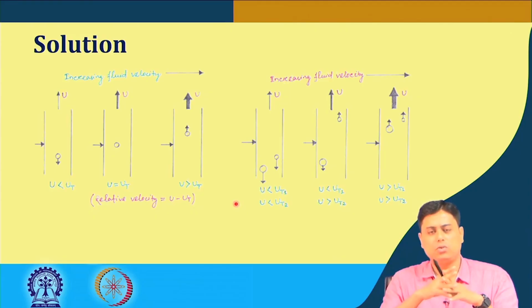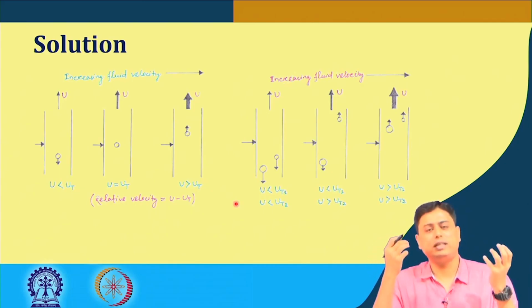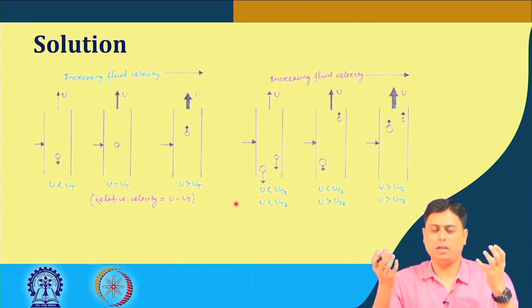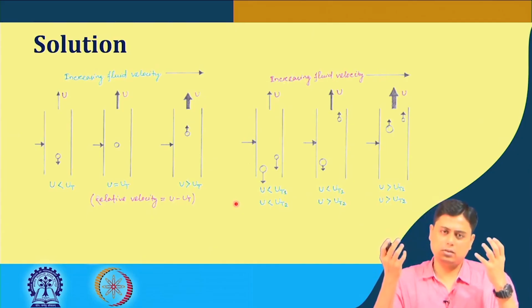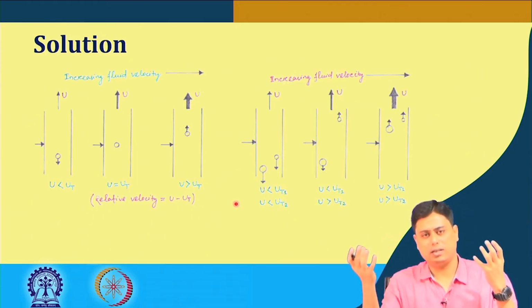So the bottom line is that we must avoid the overlap of terminal velocity range, since there is a range of particle size and two different densities. So we have to think of the two extremes. There is a heavier material and a lighter material. Heavier material is A, lighter material is B. Consider the heavier material with the smallest size, and the lighter material with the bigger size.